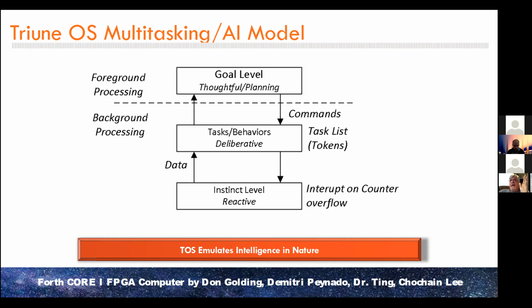There are flags associated with each one of those, and one of them is what motor override I would do if the sensor sees something, like say a left whisker, I would want to turn right, or a right whisker, I want to turn left. So that's all done automatically.